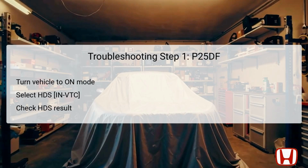For the first troubleshooting step, start by turning the vehicle to the on mode without starting the engine. This step allows for the initialization of the Honda Diagnostics System (HDS). Once the system is activated, select the In VTC option on the HDS interface. The HDS will conduct a diagnostic test on the VTC system. Pay close attention to the results displayed.